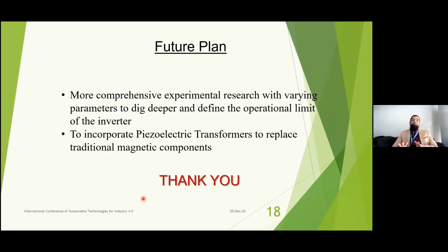Our future plan is more comprehensive experimental research with varying parameters to dig deeper and define the operational limit. We are offering this inverter, so we need to know what maximum power we can offer with this circuit. Also, we want to incorporate the PZT piezoelectric transformer to replace the magnetic components, because a PZT is a very small device. You can replace the resonant tank with a PZT transformer, so we can reduce the size of the total circuit.